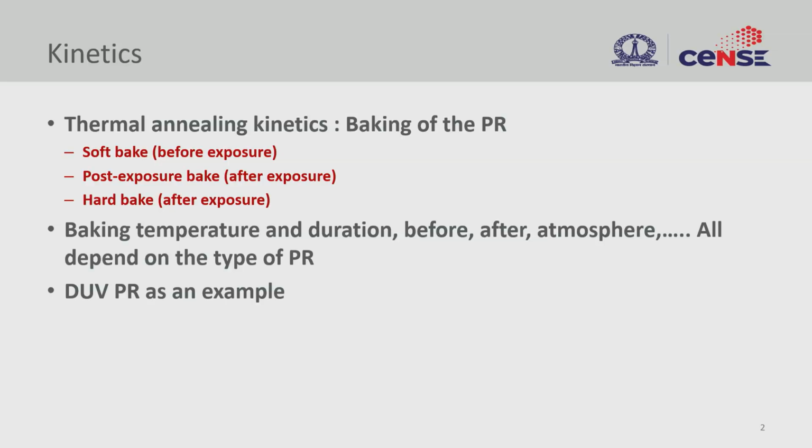And the kinetics also is pretty important. What kind of absorption you're looking for, and how the sensitizers and the resins are going to contribute to this absorption, is also very important. So when you are developing a resist, make sure that the right combination is used in order to achieve the desired result. In this particular lecture, we are going to look at the kinetics of photoresist, and particularly when you expose the material, we know what is going to happen.